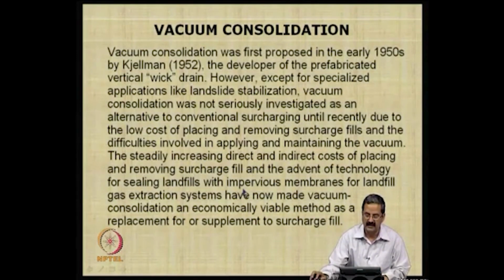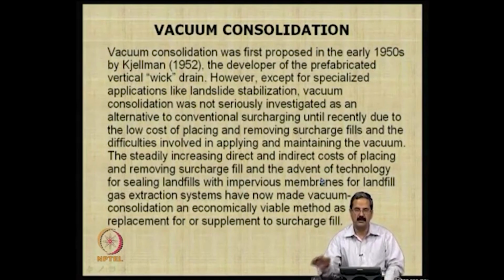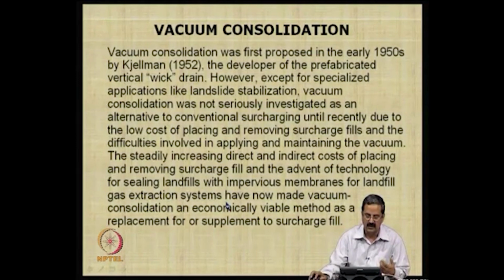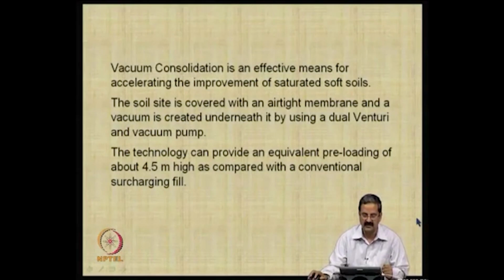With the advent of technology for sealing landfills with impervious membranes, geomembranes, and landfill gas extraction systems, vacuum technology has also improved. It has become more economical and viable as a replacement or supplement for surcharge fill.